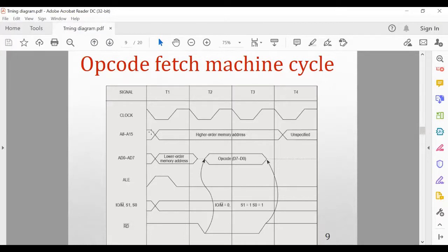Now the shape of these lines signifies that if your address is like 8000, assume that is your starting address. If it is converted into binary form, what will be the binary levels? 1000 0000 0000 0000, clear? So in total in the 16-bit binary form, only one bit is 1, that is high, and all other bits are low, that is 0.